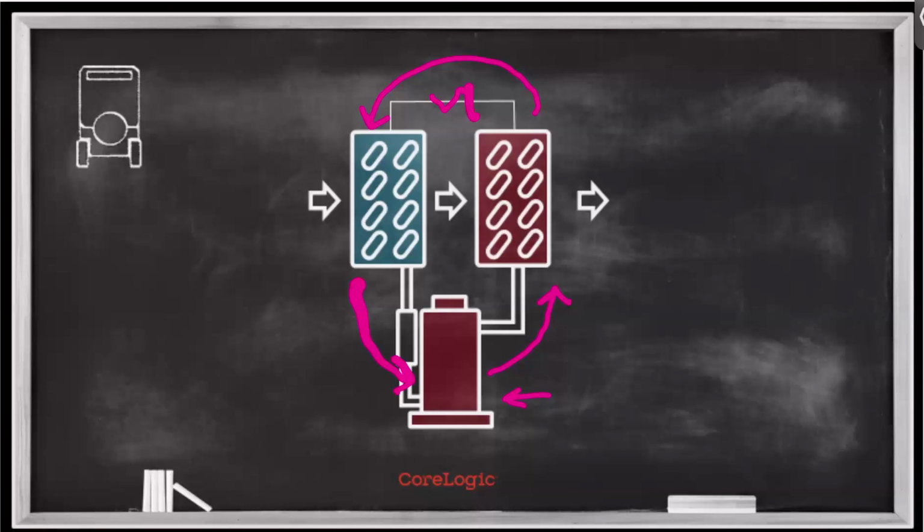What makes the magic in a refrigeration system is that on the first side, side number one, we are compressing a bunch of this gas. We're concentrating that refrigerant gas. This restriction device in the middle in coil number two is creating the opposite effect on the backside. We're expanding the gas. Okay.